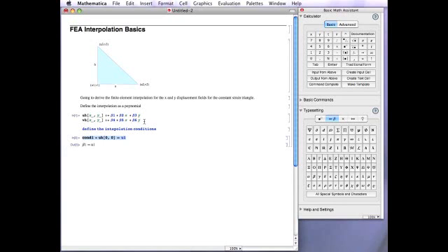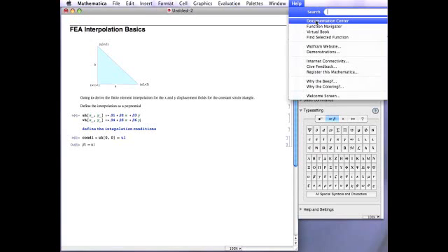I should have mentioned, I'm sorry, to evaluate an expression in Mathematica, you hit Shift and Enter. Okay? So Shift and Enter. I should have been a little careful about that. Probably the best thing to do, if you've never used Mathematica before, is go to the Help, and I think there is a Getting Started thing.